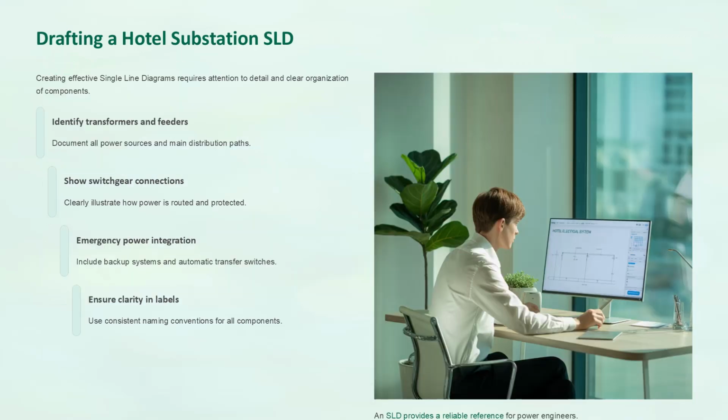Drafting a hotel substation SLD. Let's discuss drafting a hotel substation SLD. The process begins with identifying all power sources and feeders. Switchgear connections are represented clearly. Backup systems such as generators are integrated into the diagram. Automatic transfer switches are included for emergency response.